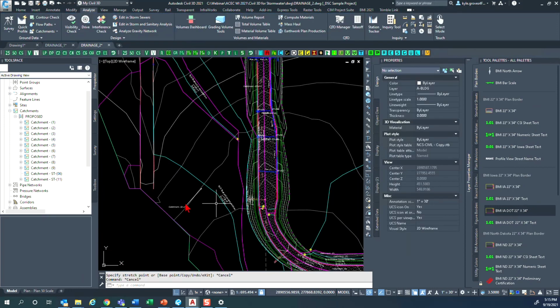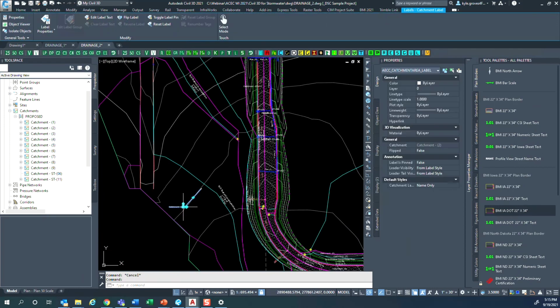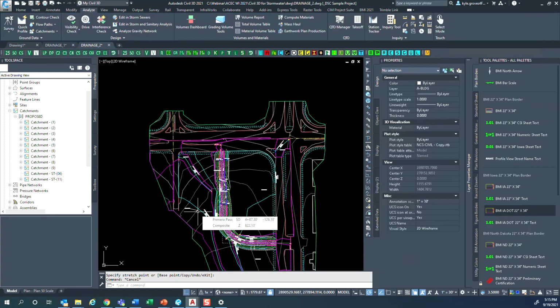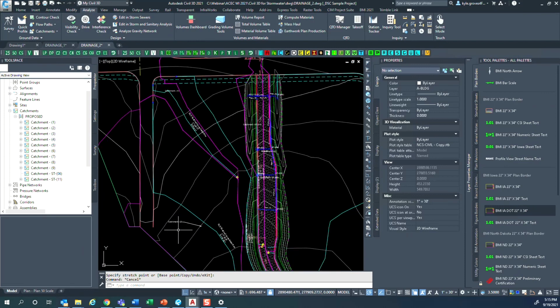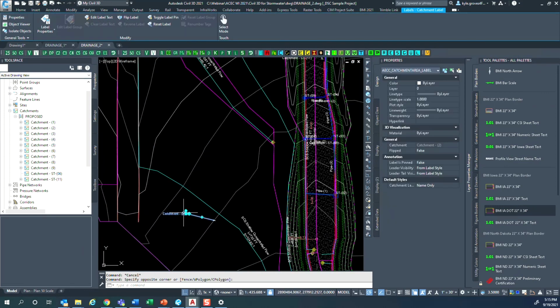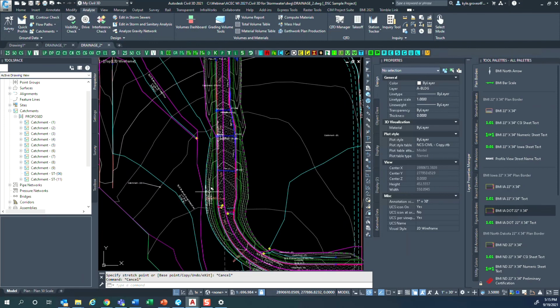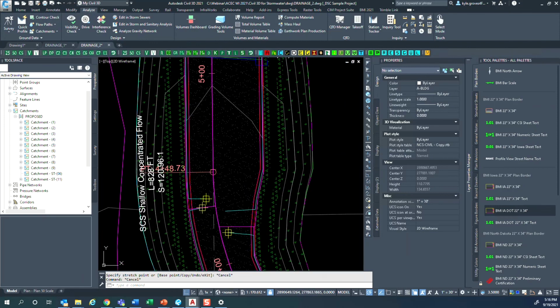And then it'll have those various segments on it. So just a couple of kinks about that. If you have a U-shaped catchment area or some sort of non-regular shape that wraps around stuff, you may need to play with your catchment area label settings, and you may need to actually disengage the leader on that.